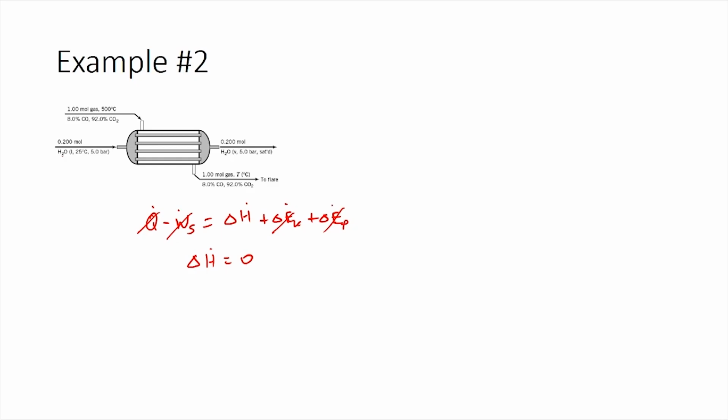This is useful because we are not trying to calculate heat transferred here, we are trying to calculate the temperature. So, for this, we would write the delta H dot in terms of temperature, because we can get Cp value in terms of temperature and perform integrations, which will give us a polynomial of temperature which we can solve to get the value for temperature. So, let us try to do that.